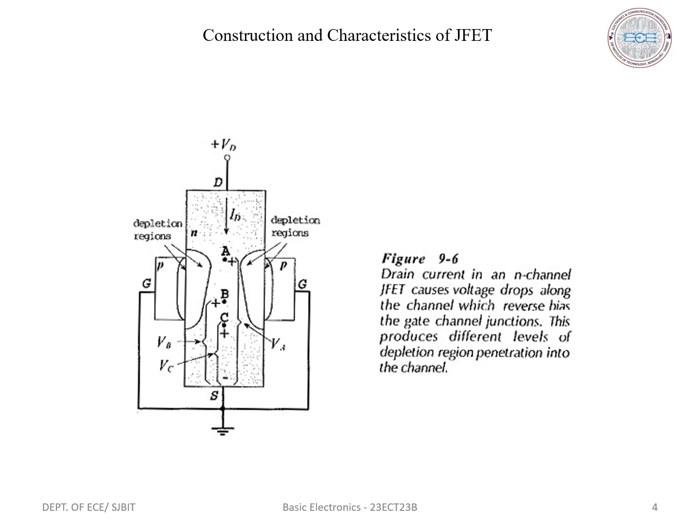Thus the gate source voltage controls the drain current. The gate channel PN junctions are maintained in reverse bias so that the gate current is normally low. The IG is lower than the base current of a BJT. The name FET comes from the fact that the depletion regions in the channel are produced by the electric field at the reverse biased gate channel junctions. FET is unipolar because the current flow is due to one type of charge carrier, that is electrons in case of an N-channel device.